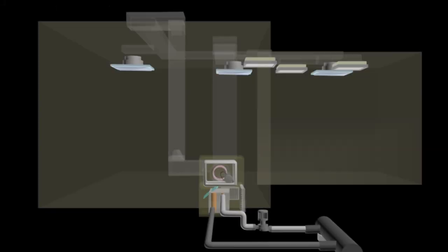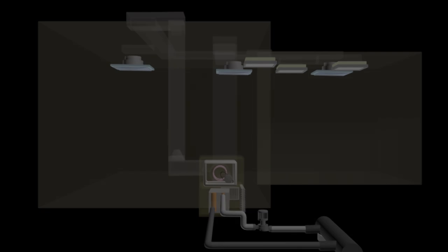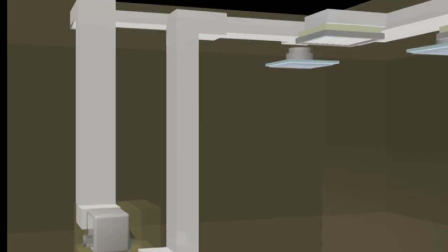For the airflow system, it is operated using an auxiliary fan which creates the air cycle from the room and mixes it with fresh air from the outside to the air handling unit and returns back to the room. The type of fan used is a centrifugal fan, powered by a motor and connected through a belting. The air flowing through a channel is called ducting.